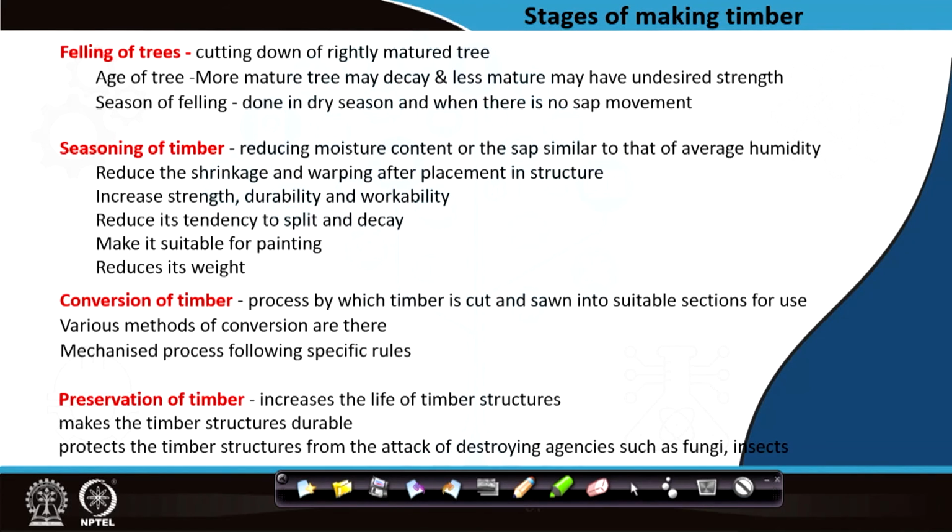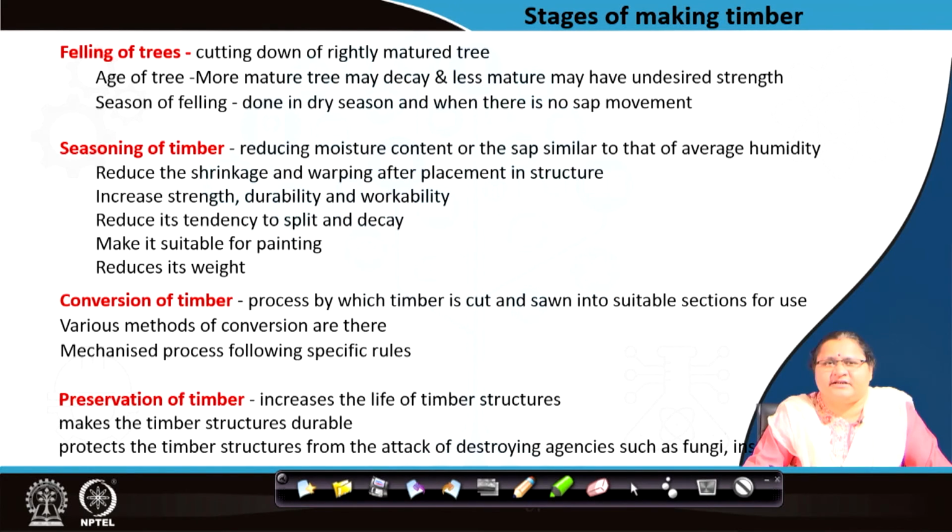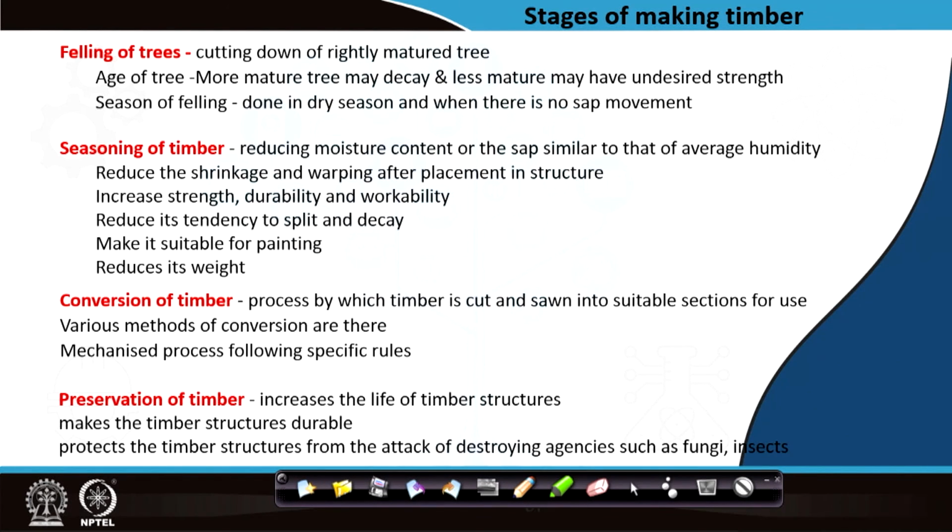So, this preservation process protects this natural resource from attacks of fungi, insects, microbes, termites, etc. Yes, the term preservation refers to when it is put to use. So, once it is put to use, we need to preserve that timber and increase the life of the member so that we do not end up destroying it by external agencies like fungi, insects, etc.